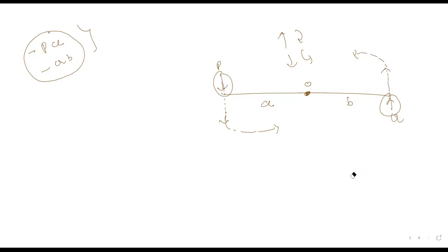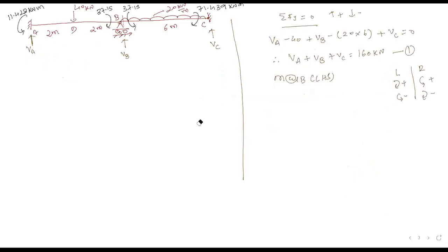From now onwards you have to decide the direction of moment by imaginary extension of the force in upward or downward direction, whatever direction is given, right? So now let me calculate again. Just see here. Now tell me what is the direction of VA force about point B. Imaginarily extend that force in the upper direction and give me the direction. Let's see which direction will come, clockwise or anti-clockwise?